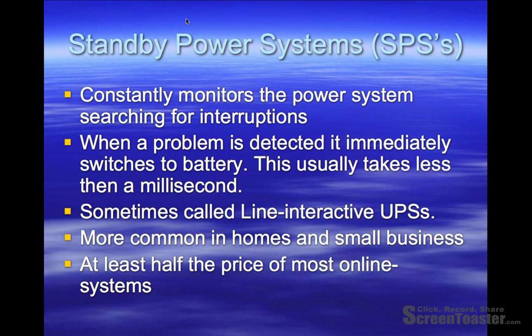First off, I'll talk a little bit about the SPS, or the standby power system. The SPS constantly monitors the power coming into your computer, and it constantly searches for interruptions. When it detects a problem, it'll immediately switch to battery. In most cases, this will take less than a millisecond, so almost instantaneous, obviously instantaneous to us. Sometimes SPSs are called line interactive UPSs as well, but most commonly they're SPSs.